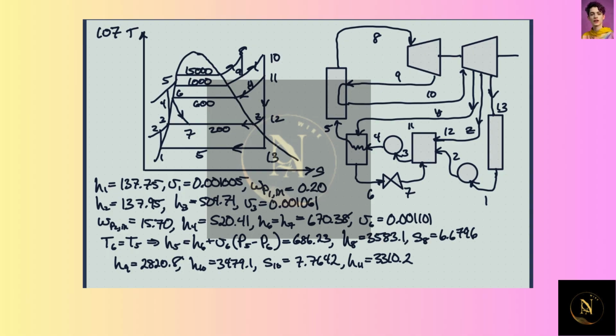And so we're basically just looking at how this stuff coming out here gets back up to here. So it has some enthalpy here, and then we put some mechanical work into it because of the pressure difference. We lose some pressure here, but we gain some pressure here. So the thing is that it's a saturated liquid here. It's also pretty much a saturated liquid here at the same temperature, roughly.